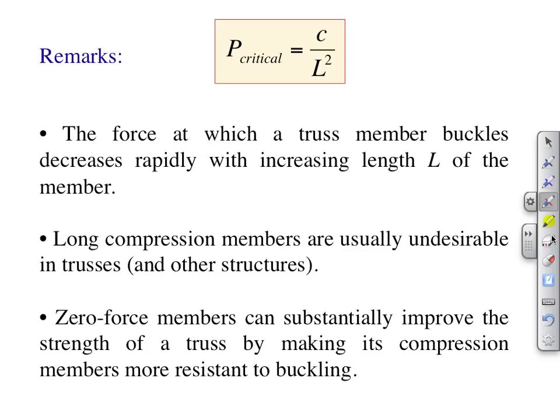Herein lies the value of our zero-force members. Even if it isn't carrying a load, a zero-force member can break up an unsupported span into two shorter members, substantially increasing the critical buckling load of each of them. Of course, this only works if the members are in compression.